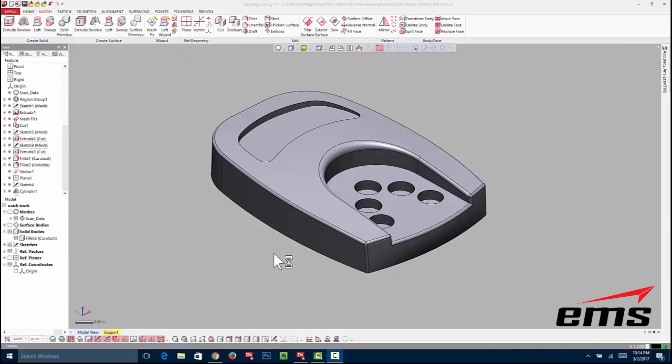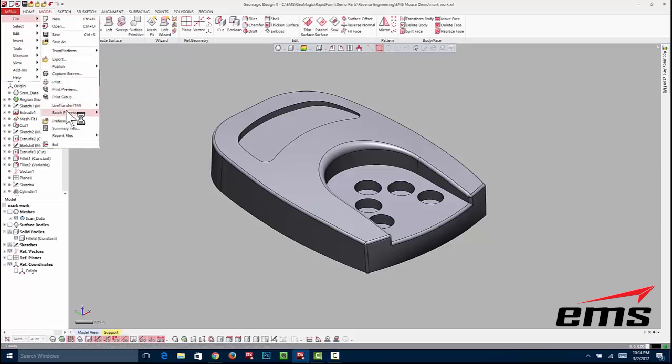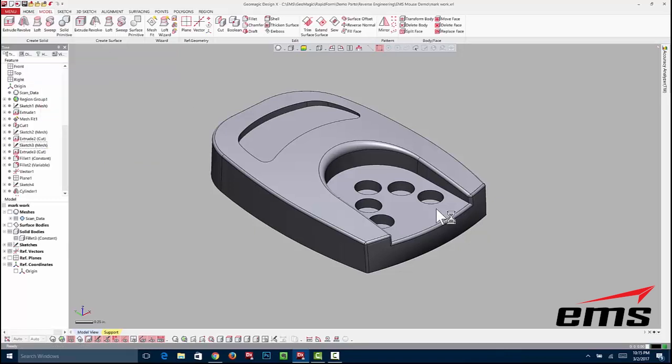The advantage of doing that is then you have a CAD model in your host CAD system with the history tree. Now, the live transfer is not perfect depending on what CAD system you're going to, anywhere from 50% with a product like Creo or Pro-E, all the way up to about 85-90% with Siemens and SolidWorks. Same as Solid Edge, because they all use the same ParaSolid kernel. Inventor works pretty well, AutoCAD works pretty well. So that's another real advantage, is now you get a history tree model in your native CAD system that you can work with.